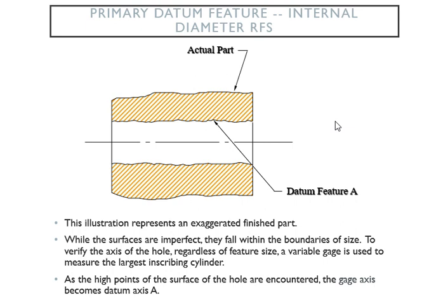For the surface, the very first example in the beginning when we started, it's really easy because you can picture the gauge as a block, so it's pretty easy to find the plane. But for the axis, it's inside of the cylinder, and your gauge is also kind of like a cylinder, and the cylinder is inside of the cylinder. So you have a little bit of an issue finding the axis.